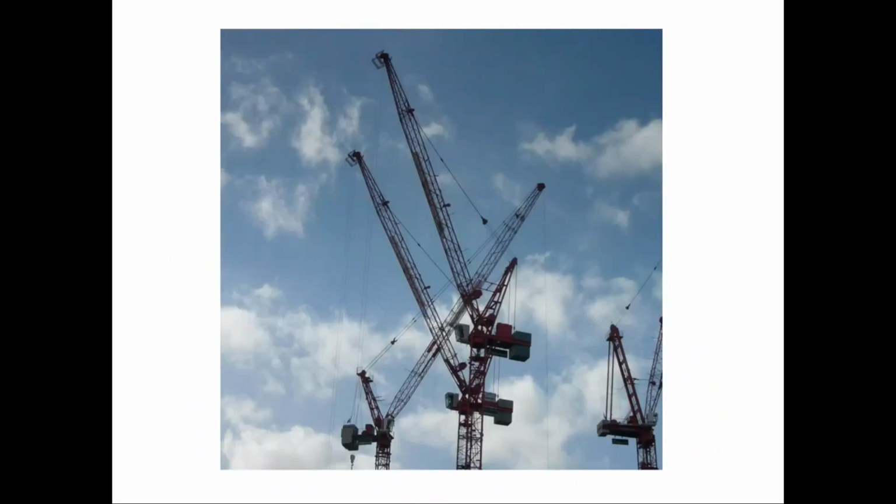Of course, every crane is a cantilever. You now realize that. All the load that's coming down here is in pure tension. That's in pure compression. And that's equal on the other side. That mass here is equalizing whatever is the mass that is going to be lifted by the crane. There's some nice triangulation going on here. That, again, pure tension, back to that compressive element there. Compression, compression, tension.